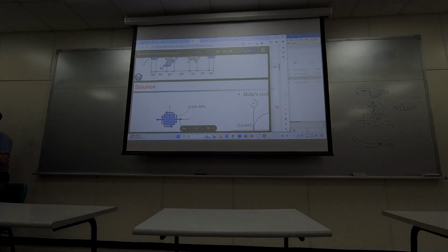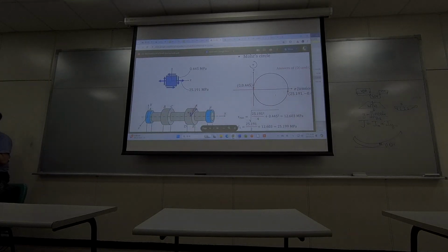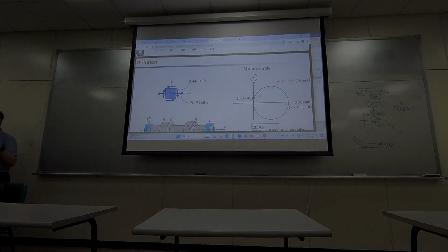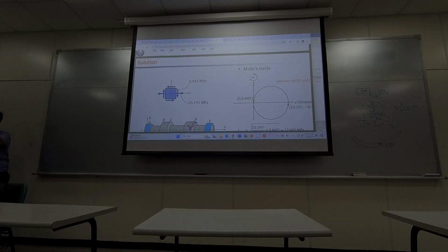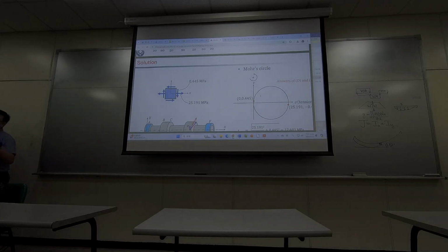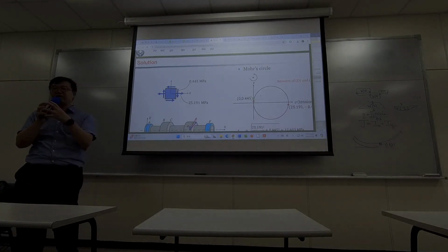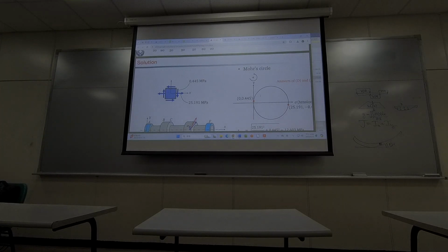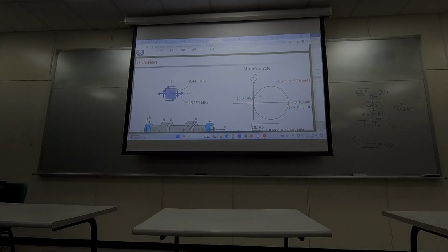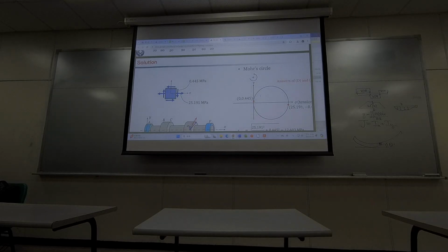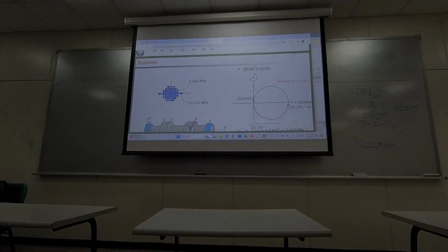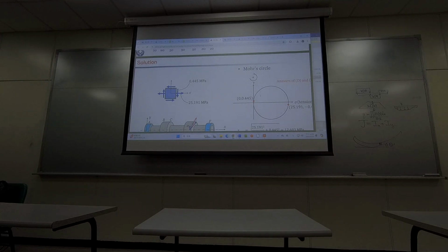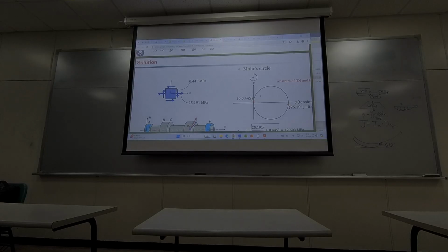Because tomorrow, after I talk about Mohr circle, you will realize Mohr circle is a way to help you observe a single point in different orientations. So if forces are being applied to an element at a point, and you are viewing this element along a certain coordinate, you may not figure out along which orientation is carrying the strongest load. So Mohr circle helps you figure out that you need to rotate your coordinate system in a certain way, or view this in this way.